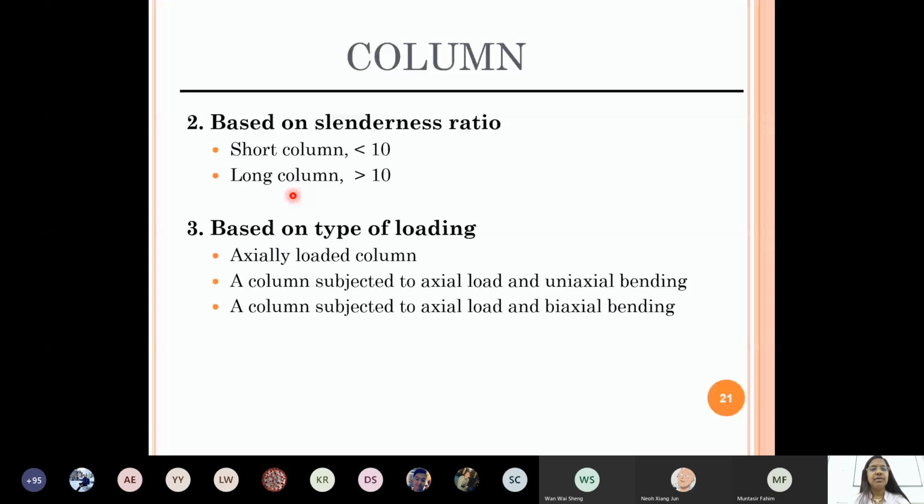Okay, we will do this calculation when you go for actual design. Again here it's cross section by height, there are different types of calculation, but mainly cross section by the depth here, because you have square, circular, rectangular, right? So they will have a ratio, and if the ratio is less than 10, short column. If the ratio is greater than 10, long column, right?